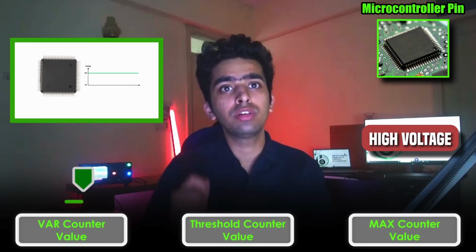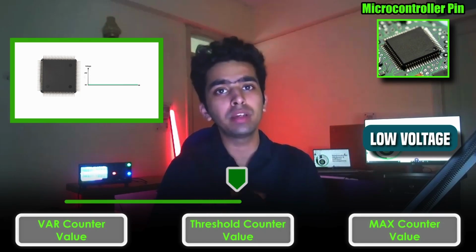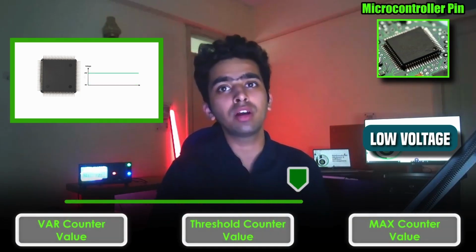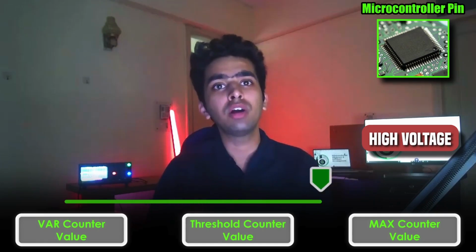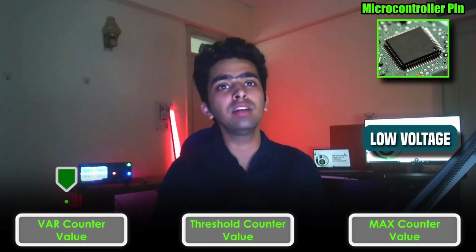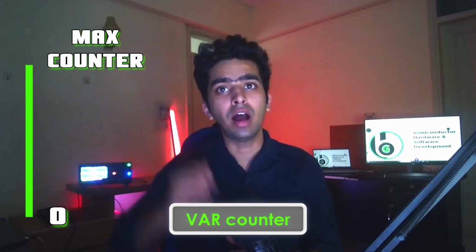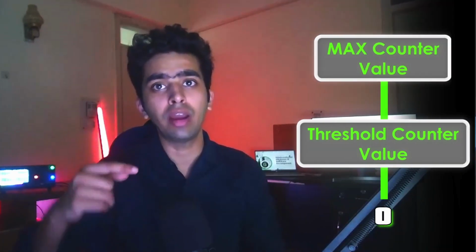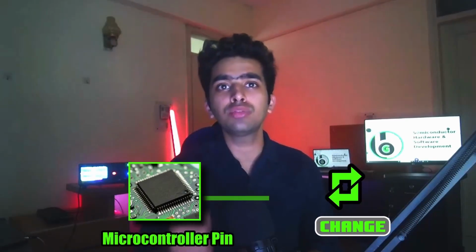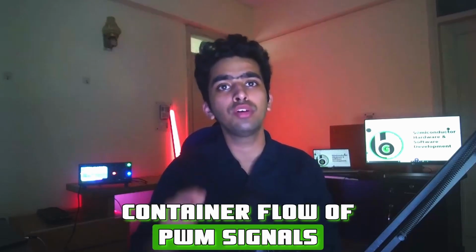When the var counter reaches the value of the threshold counter, the voltage signal of the configured microcontroller pin is changed. And after that, when the var counter value reaches the max counter value, again the microcontroller pin value is changed and the var counter resets to 0. And then this cycle keeps on going. So the var counter will count till the max counter, and after that its value will reset to 0. Starting from 0, it will start incrementing, and on reaching the threshold value and the max counter value, every time the state of the microcontroller pin is changed, and this cycle keeps on repeating to produce the continuous flow of PWM signals.